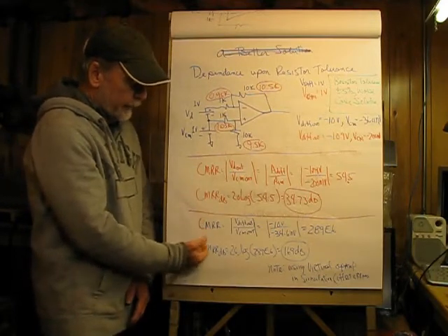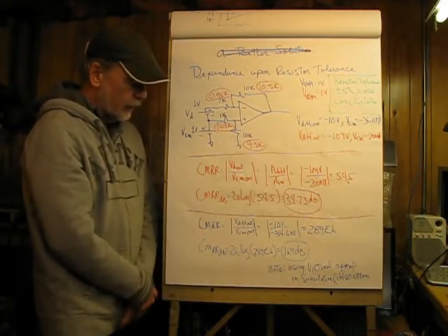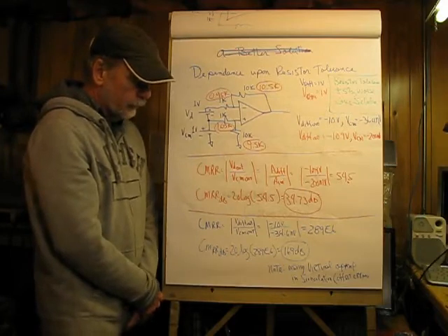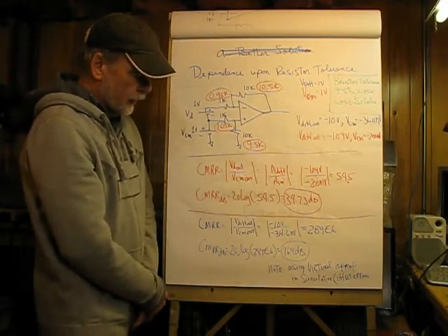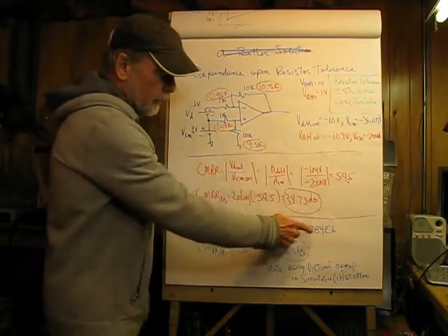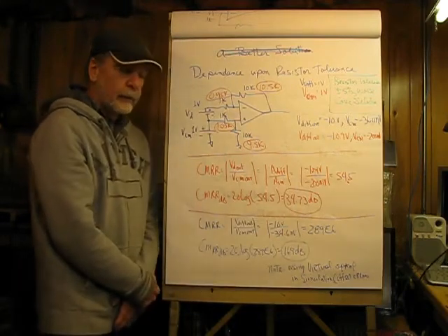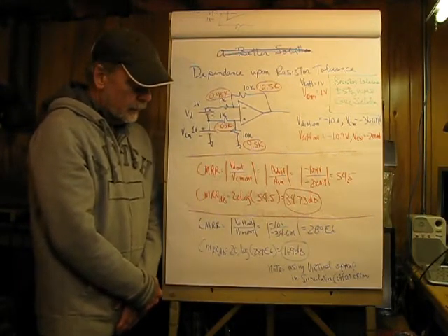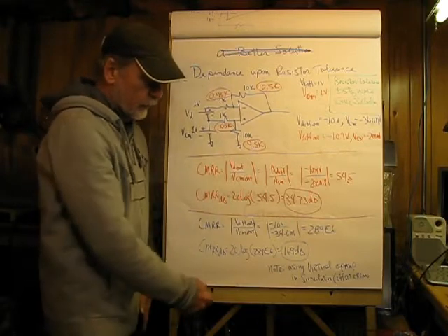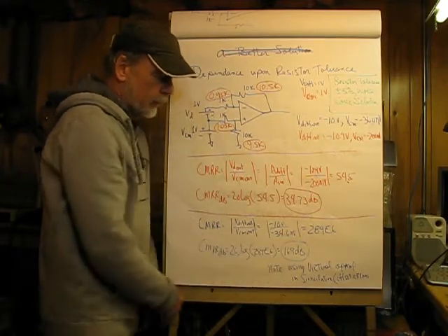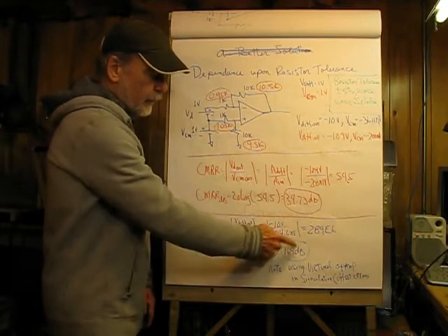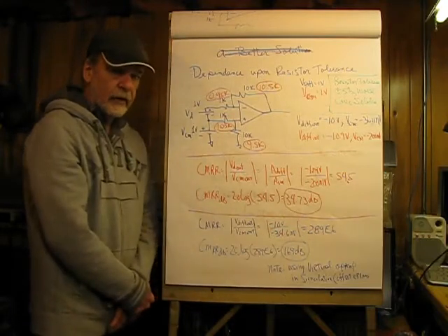Now, using the ideal, which is in blue, the actual values, and running the same equation, the common mode rejection ratio here comes out to be 289 million. And converting that into decibels gives a huge 169 dB. Now, this and this are not practical values.